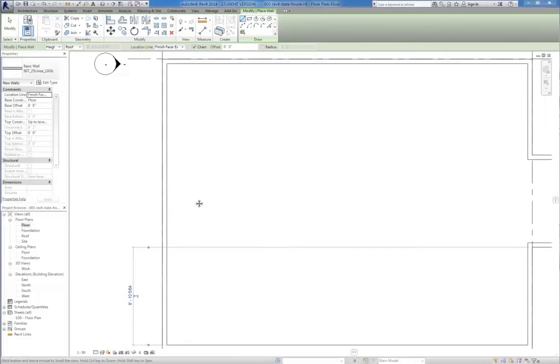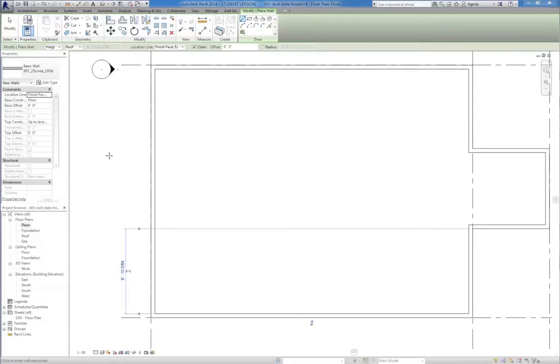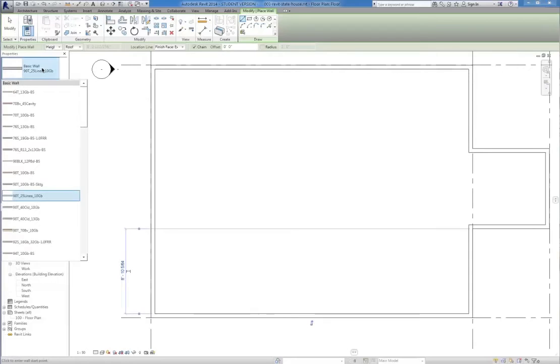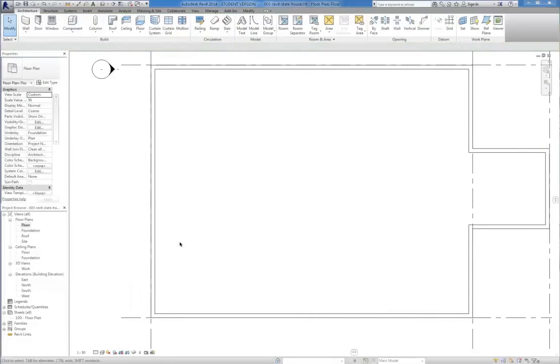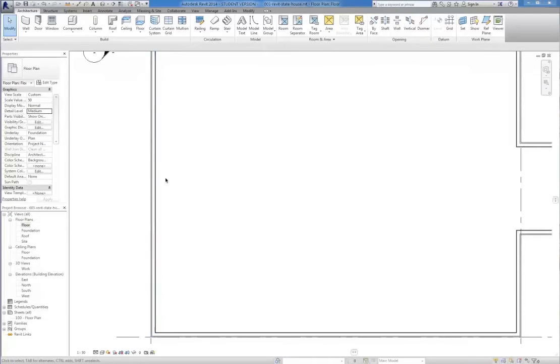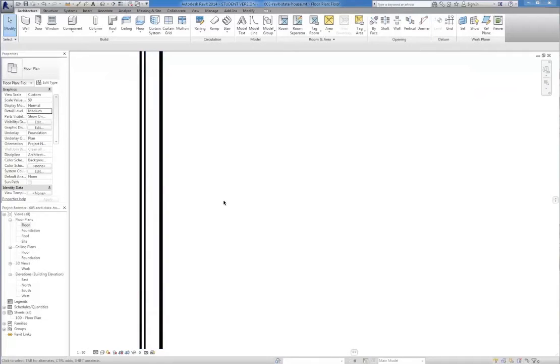So in Revit, to get it to show the structure of it in the plan view, you have to select nothing, or select just the floor plan, and then go, I think it's detail level, and then medium. Yeah, see how it changed then. That's the level of detail it's giving us, which is cool.